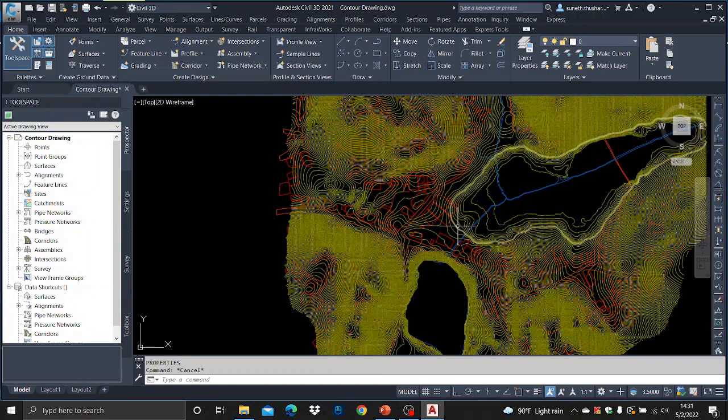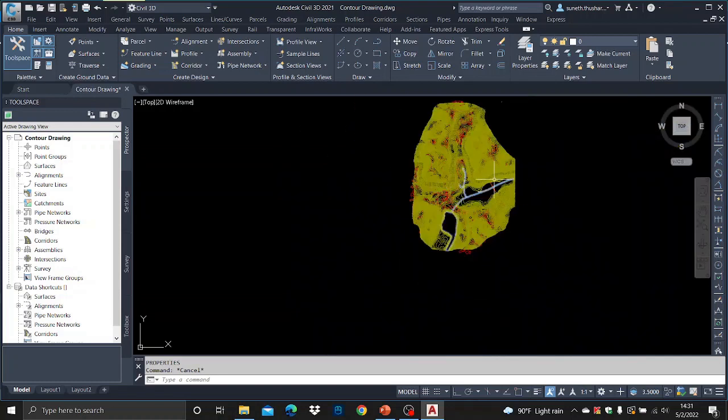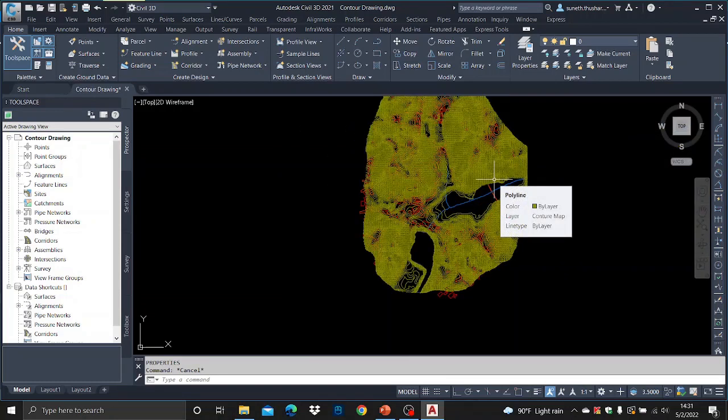Please understand that when we are going to design a new road, we usually have a contour survey through a drone survey. We do a drone survey and then we extract the data for the contour survey. So this is such a file. Here we do not have any points, so what I described in my previous session, you cannot use for this one. This is the contour file. Let us understand how we can create a surface using this.